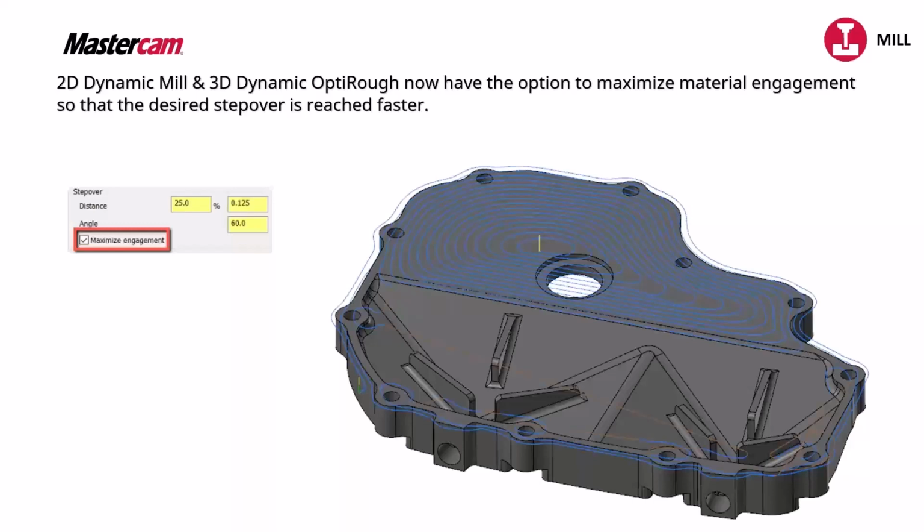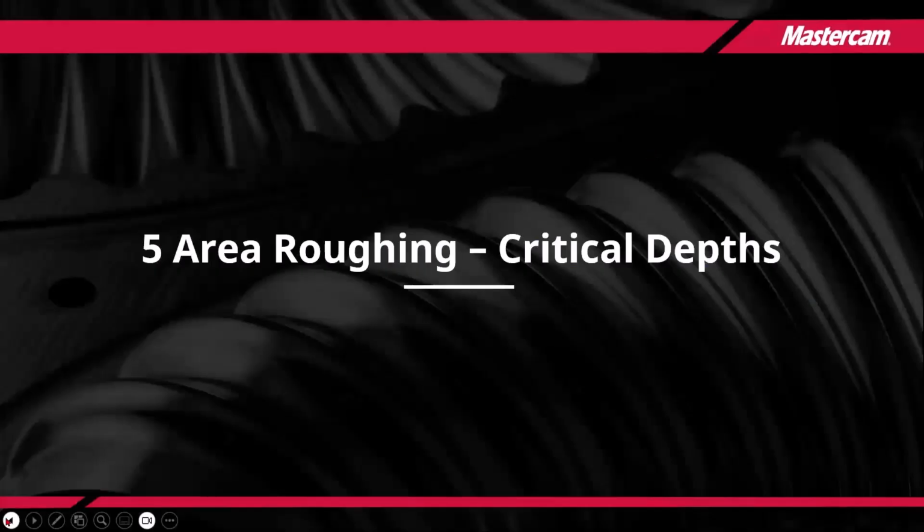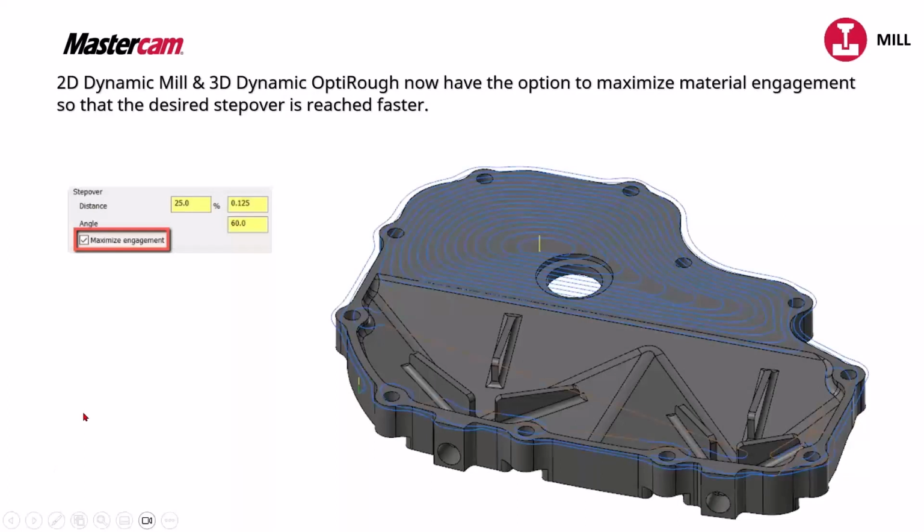I wouldn't have it on all the time. For cases where I'm using a really long end mill and I want to do a full axial cut with a very small step over, depending on how small that step over is, maybe if it's not that small, maybe if it's like 25%, I don't want to be leading into that instantly in every case, right? I might want to gradually lead into that. Depending on the type of work you do, maybe you do have it on all the time, but I think for me, I would have it off by default and then only turn it on in those cases where I want to use it.